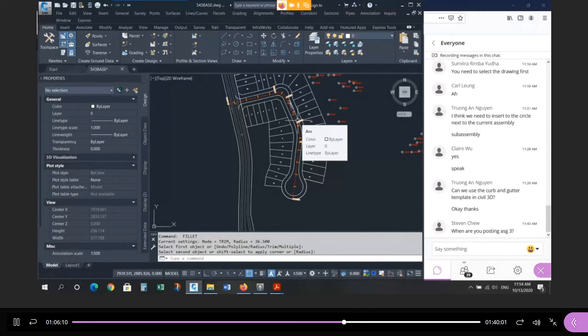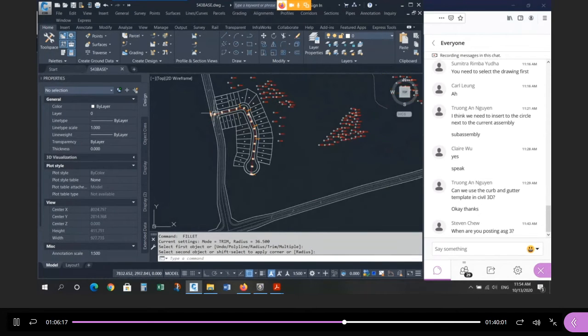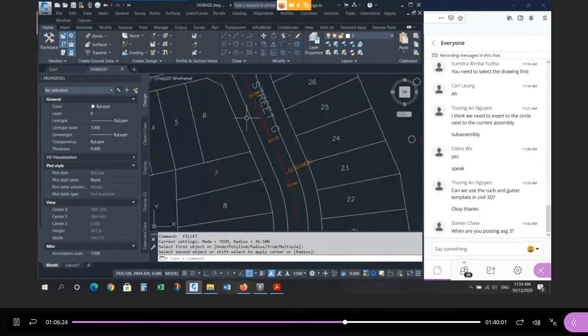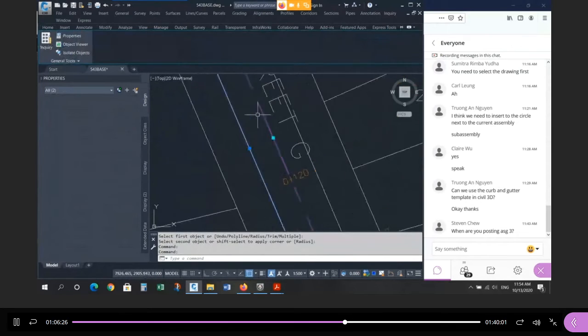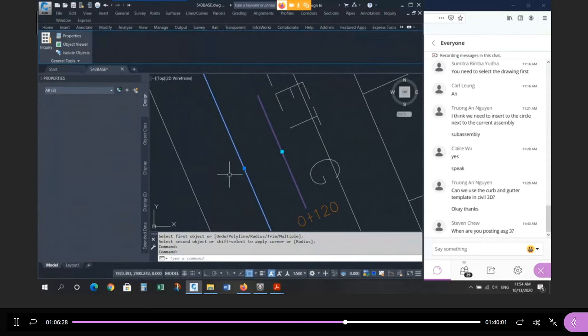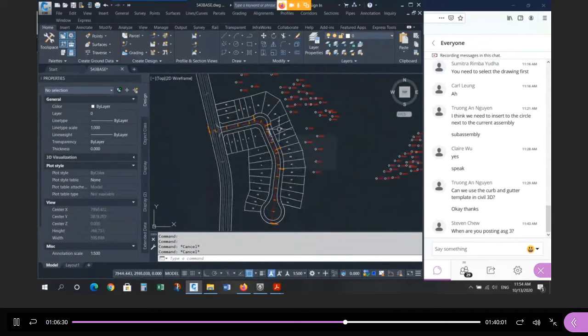Okay. So those of you who got 4 out of 4 on the third item did this perfectly. If you didn't have the intersection right, you lost a mark. If you had the elbow wrong, you lost another mark. If you got the cul-de-sac wrong, you lost a third mark. And if you didn't have the standard width, if this distance was not 4.25, another mark, right? So you had to have the standard width correct, and then the 3 special areas: intersection, asphalt elbow, and cul-de-sac crescent correct. So that was the 4 marks there.